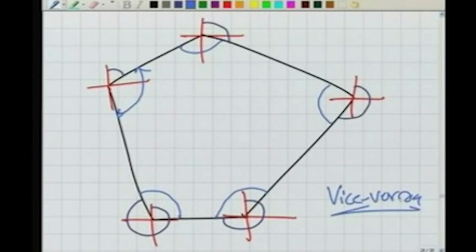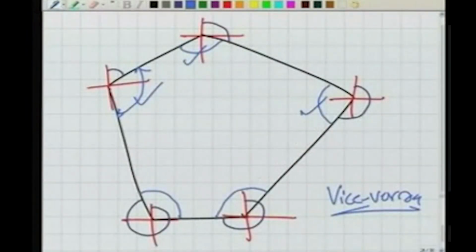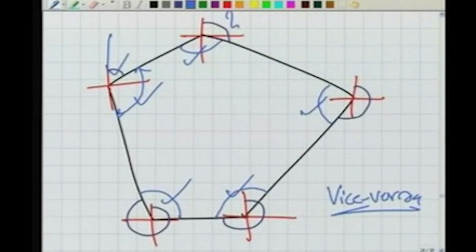If you know the internal angles of all the lines and the bearing of one line, let's say you know all these, and you know the bearing of one single line, then all these can be determined. Whatever system you want, in WCB or QB, everything can be determined.